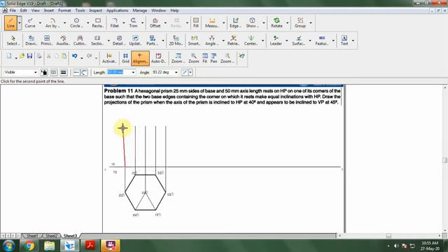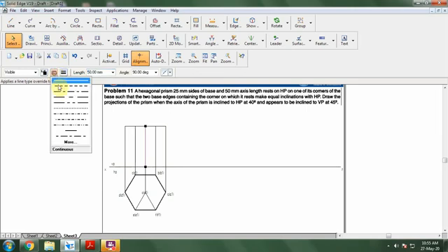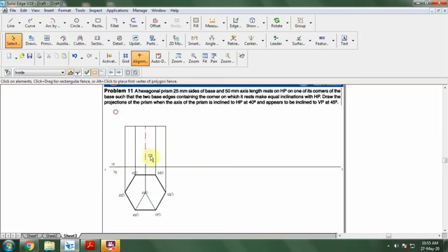Again, this height also I'm going to take 50 at an angle of 90. So lower also I'm going to join the base. So now this is the axis line. I want to make that the axis line, so I'm going to select that and make the thickness 0.5 mm.